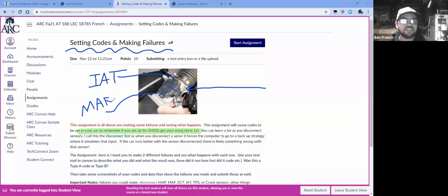So with this activity, if you were to disconnect the mass airflow sensor, and all of a sudden the computer lost both of those inputs, some cars will maybe hiccup for a quick second, and then they won't skip a beat. In fact, what you'll find out is that a lot of cars, mostly your domestics, your General Motors, your Fords, your Chryslers, you drive them around, and other than the check engine light being on, you probably wouldn't feel that the car ran any different at all.